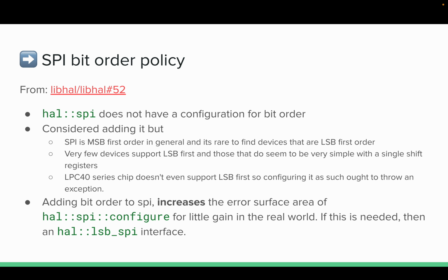Because it's going to be one of those things where you could wrap your SPI driver in something that reverses your bits, provided that byte order doesn't also change. And if it does, then that becomes another can of worms. Let's assume that it doesn't. Actually, no, because if you change your LSB order, it doesn't change your byte order. So yeah, you can just have a wrapper that does that for you for every single byte you want to transmit.